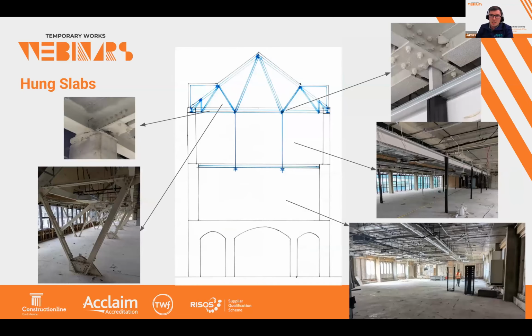Another interesting example of building we came across recently is a structure with some hung floors. So this building's been built and the roof truss supports the second floor, so that the first floor level you've got a big open plan area on site. Now there's no historical information on this building, and I'm not sure the site team were aware that this was its construction when they started the soft strip. So it's a bit of an interesting one